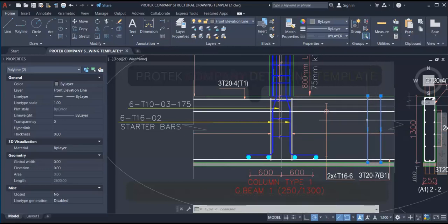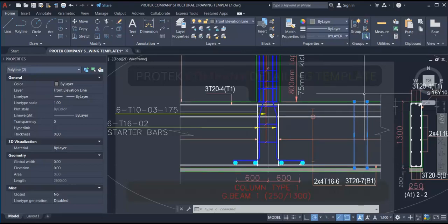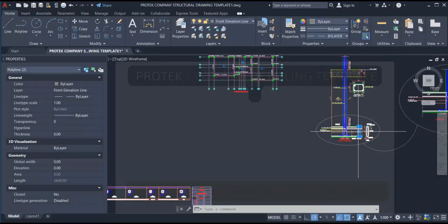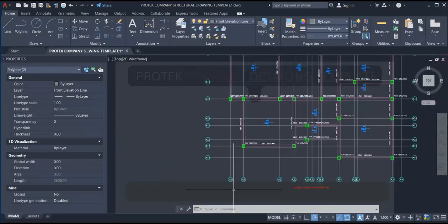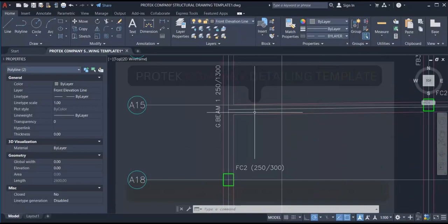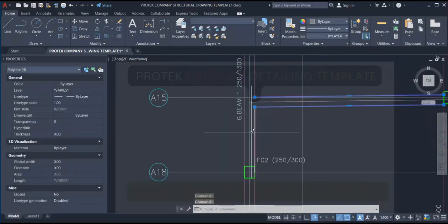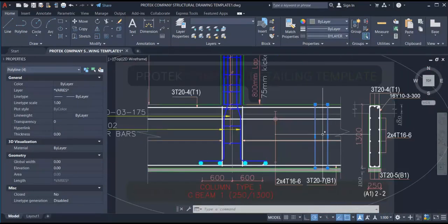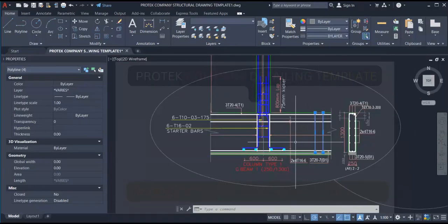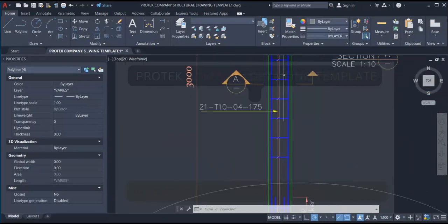There is a purpose for these two lines. They are actually telling you that there is an incoming beam being anchored in these particular provisions. If we go back to the beam layout, the ground beam layout on this axis A1, you check it very well. You notice that this is the incoming beam, these two beam lines, anchored to this major beam here. That is why you have to leave this line felt so that it can be interpretable. After which you now cut a section just like this.